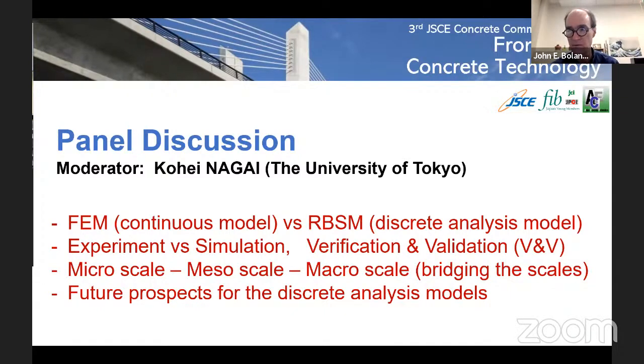And for example, we have simulated cement hydration and used cement hydration to control the time variant properties of the springs. Arguably that's transitioning scales, because the cement hydration model is based on cement particle composition, cement particle size, and water cement ratio. You're bringing all that information from a much lower scale into the spring properties.